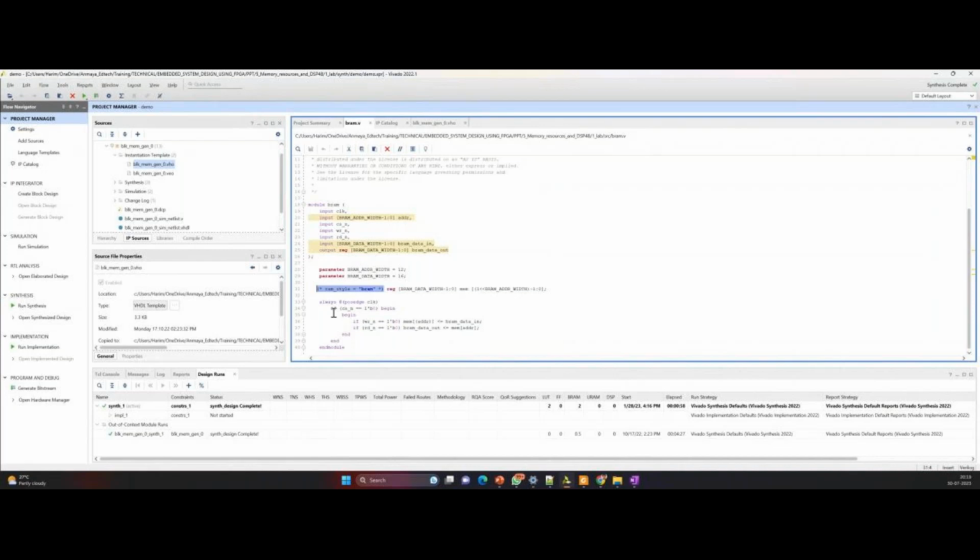There are actually Xilinx design guidelines. We have to follow those guidelines and write the code in such a way that it will infer in a particular manner. So the tool will understand, okay, you are trying to infer this, and according to that it will place and route. Clear? Yes, sir.